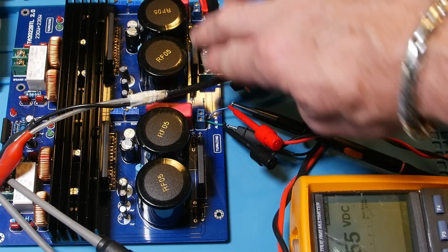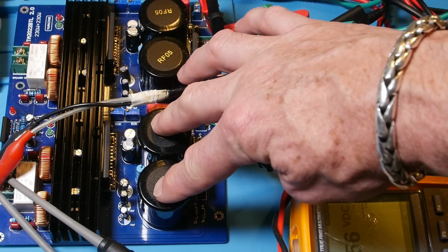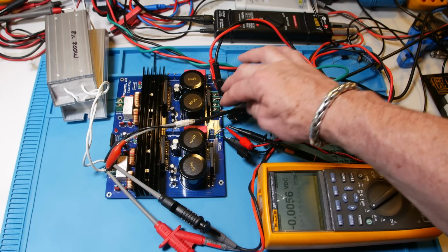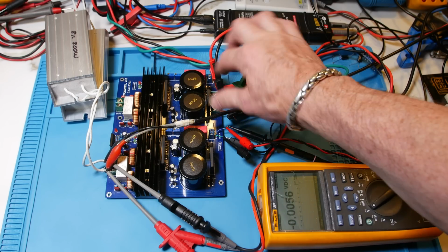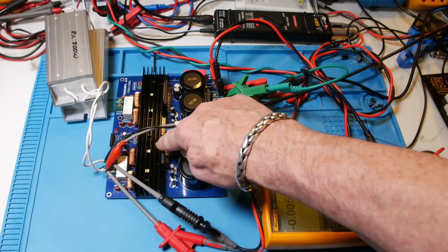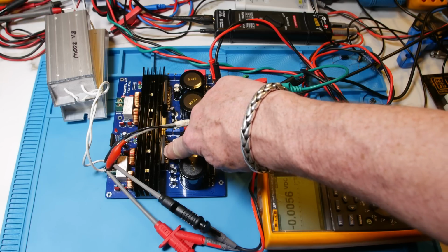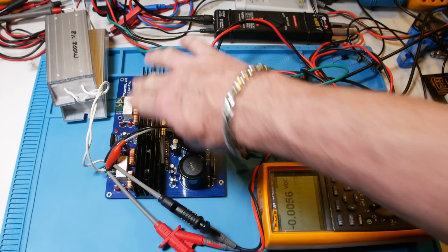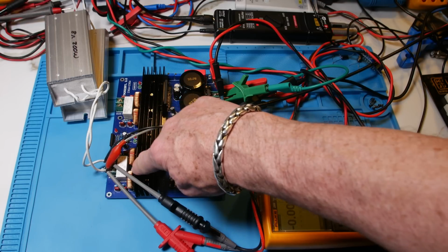So it goes through both bridge rectifiers to the capacitors and charges them up. So instead of going AC through, the diodes will steer the plus minus voltage into the capacitors the correct way. And then here is the power module for the left side and the power module for the right side on this heat sink. And then here's the output